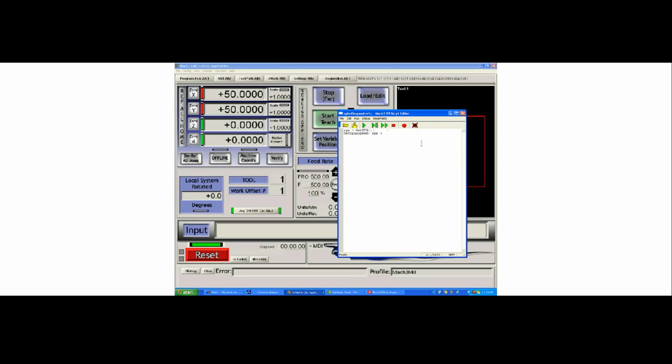You could simply, in between, say RPM equals RPM multiplied by 0.5. Again, this is a useless script, but it shows the methodology of doing a script. You can get the RPM value that has been requested, you can multiply it by 0.5, and then set the spindle speed to that RPM. It's a pretty powerful method of modifying the program.